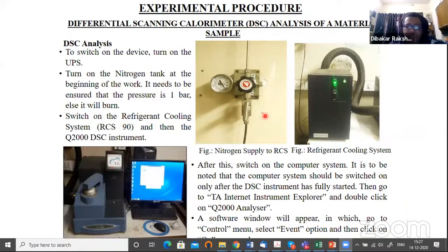DSC, that's a good question. DSC does not measure the inflammability of any particle. DSC only gives the thermograms. DSC only gives the heat storage capacity. For conducting the flammability test, you have to do some other arrangement, another type of environment where you can see when the actual phase change material catches fire.